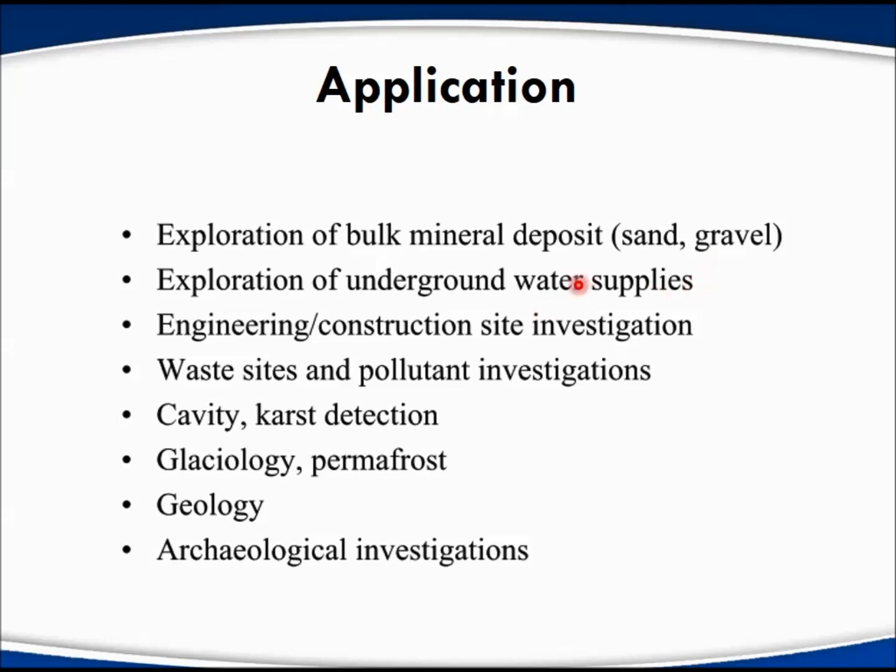And then we have utilities investigation studies, where we run the survey to identify the location of underground utilities, such as underground pipes, water supply, electrical cables or tunnels, and so on. This is when the engineer wants to confirm the presence of underneath utilities for any construction and pavement or development above it. So this technically can be categorized as site investigation as well, or they call it geotechnical engineering.